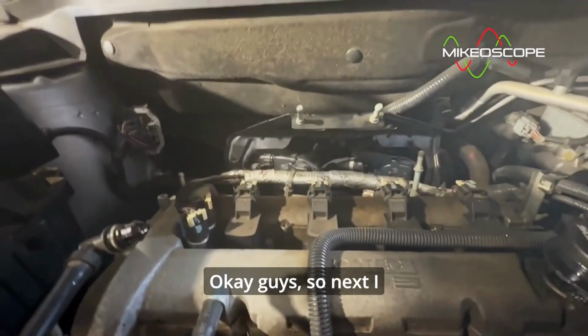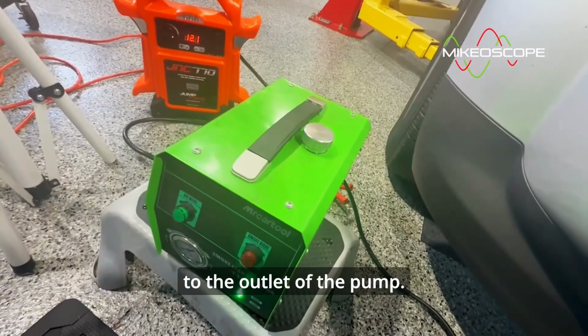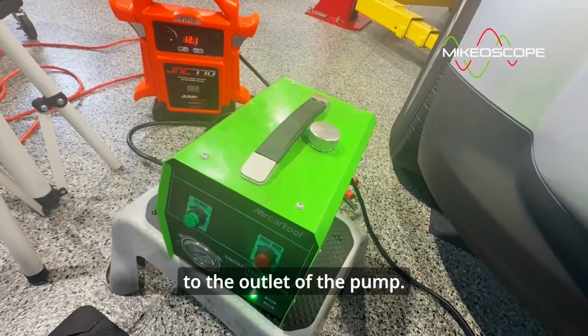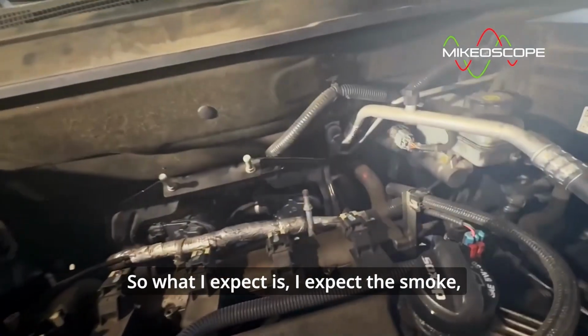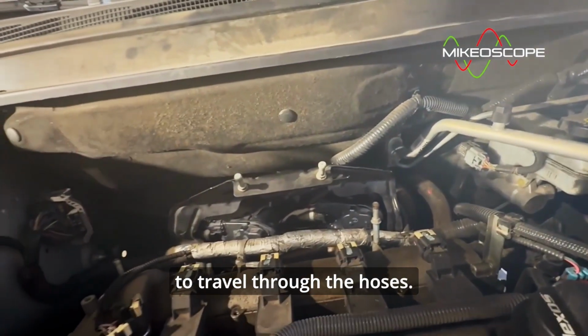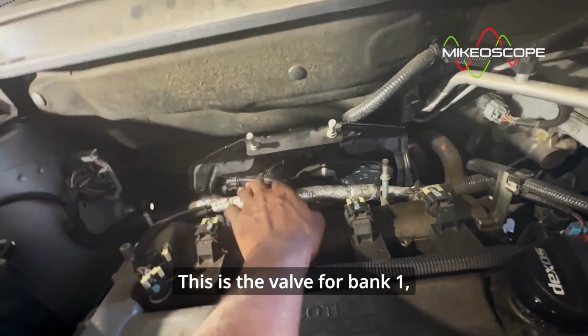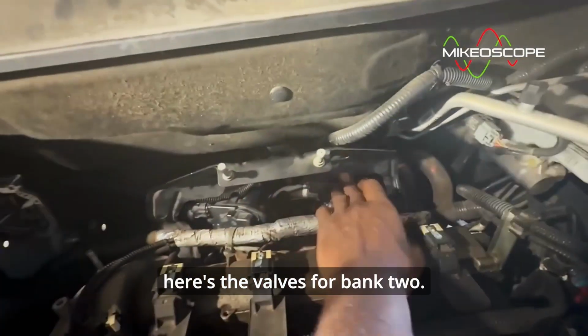Okay, guys, so next I have a smoke machine here, and I have the smoke machine connected to the outlet of the pump. So what I expect, once I turn the machine on, is for the smoke to travel through the hoses. And then when it gets to the valves, here are the valves. This is the valve for bank 1. Here's the valve for bank 2.